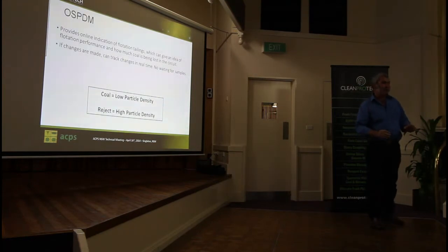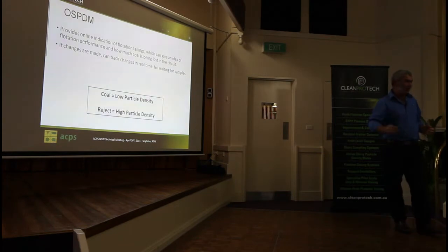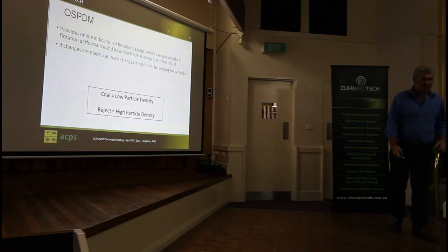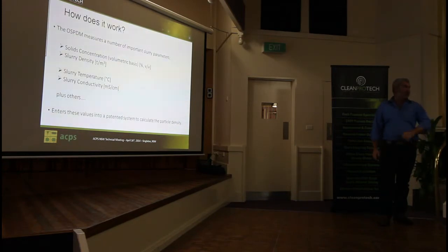It's real simple. It's interesting, when we actually had this on a plant in Queensland, we were trialling it. Back in those days, I was looking at relating particle density to ash, and actually the operators were going, why bother? It's easy, mate. Understand this: tailings, high particle density, product low. Very simple. So we actually then just forgot about the ash correlation. Just work on particle density.